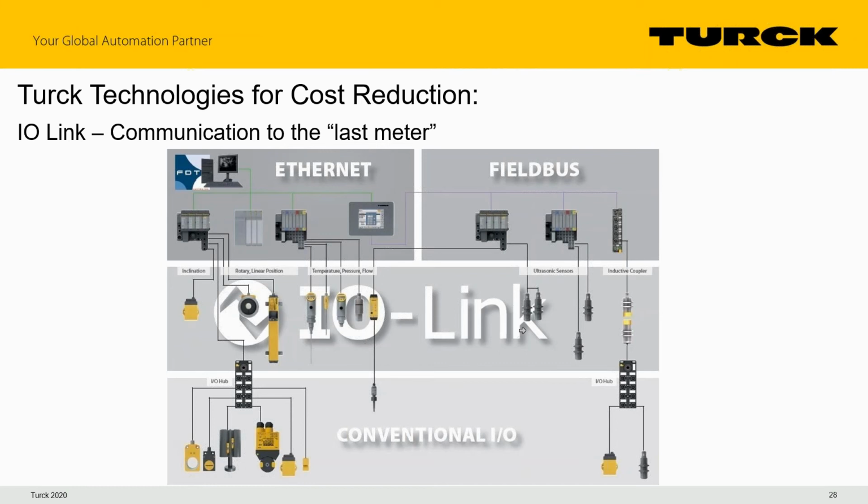These devices here look like our typical proximity sensors. So a lot of people would say, well, why would I use a proximity sensor on IO-Link? It's a pretty simple device. Well, when we put a proximity sensor on IO-Link, we get a couple of health indicators from it. It has a built-in thermistor, so we can watch the temperature, and it has a signal strength indicator. So I can tell when the signal strength is changing that my piece is not in the same location. So I can't really measure distance with it, but I know if I'm getting too close or too far away. If my temperature is getting hot, I know I've got a problem.